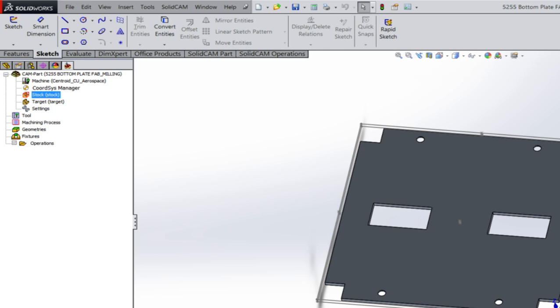So always come up with a plan for machining before you start writing the toolpaths. Make sure you can move clamps around. Now, if I have 4 clamps here, and then I'm going to change to end mills and put 2 clamps in, should I remove all 4 clamps and then put 2 clamps in? Why not? Displace your object. The object might move on me, right?